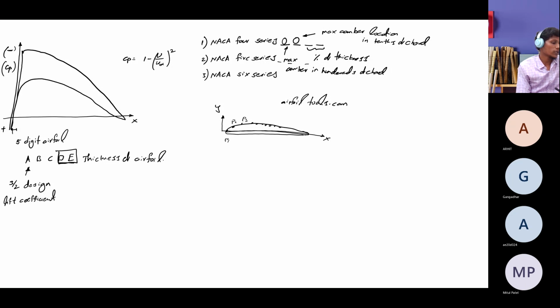And the inviscid theory can predict, if you have gone through the complete derivations of how the inviscid theory worked out for an aerofoil and how it was modeled, that dCl by d alpha equals 2 times a naught, that is 2 pi. We can model how we came to this conclusion that dCl by d alpha equals 2 pi.